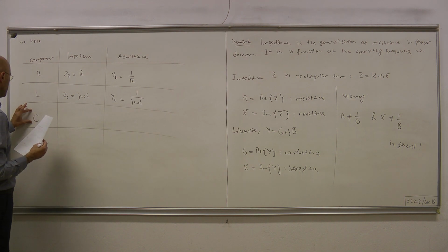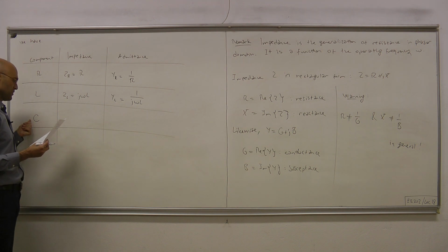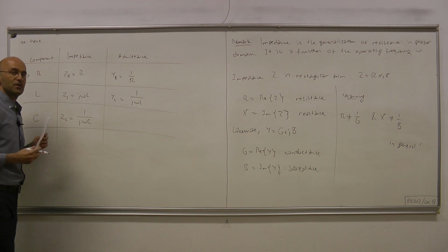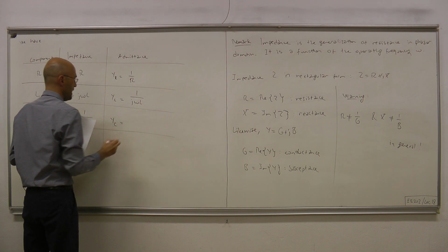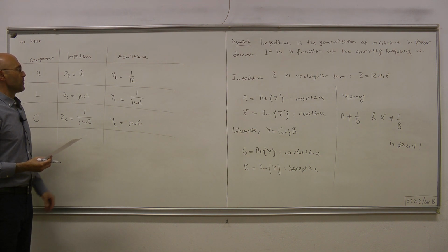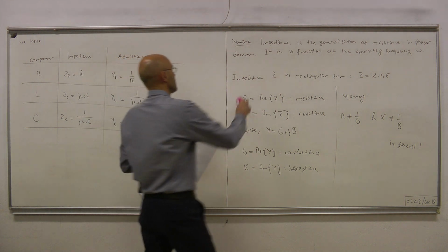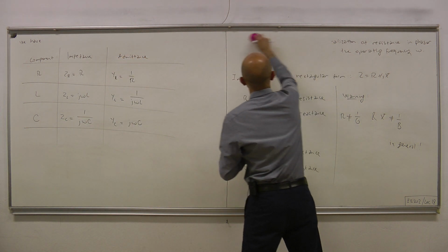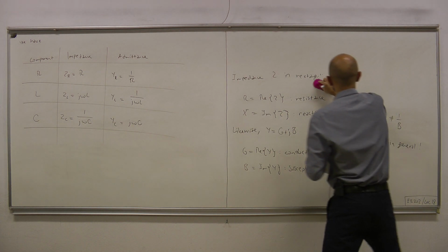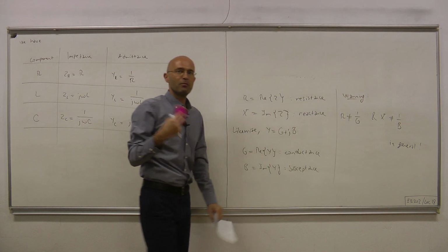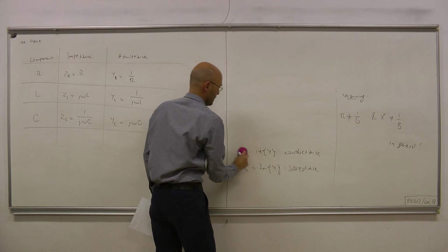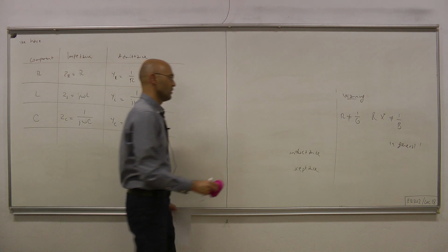And as for the dual component, the capacitor, whose capacitance is denoted by C, we have impedance equals 1 over j omega C, and admittance equals j omega C. Now, in the phasor domain, therefore, any two-port under the assumptions that we listed can be represented by an impedance, a complex constant, which indicates the ratio of voltage to current phasors.